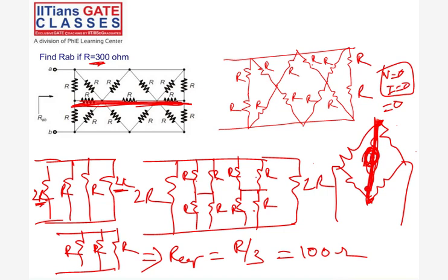In this, you have to decide looking at the circuit. If you feel it should be shorted, it will be easier, you can short it. If you feel it is easier to do it open circuit, you can do that. Otherwise also, if you see there is one Wheatstone bridge, all the resistances in it are equal to R. The total resistance is R parallel with R parallel with R, so you'll get R by 3. Of course, there is an interconnection here. Otherwise, this is a direct question of 3 R's in parallel.